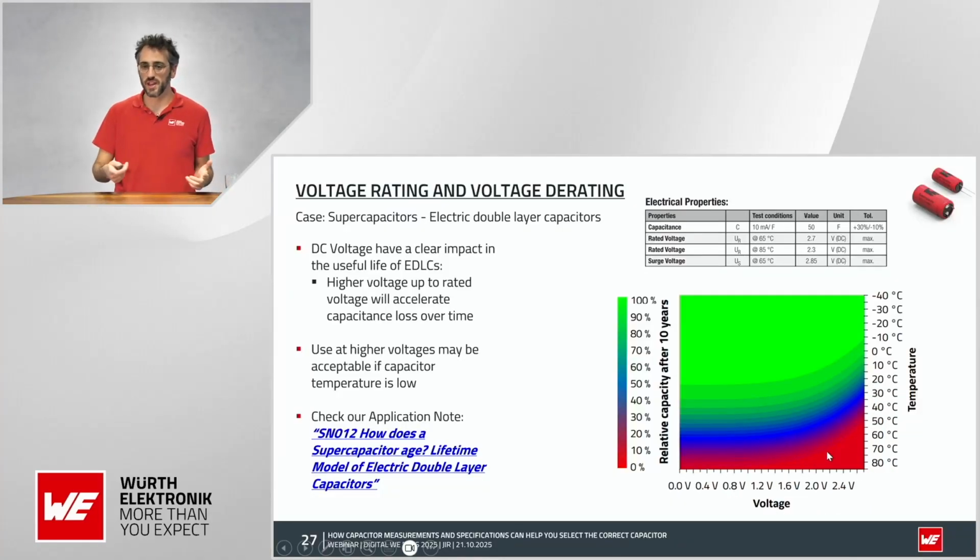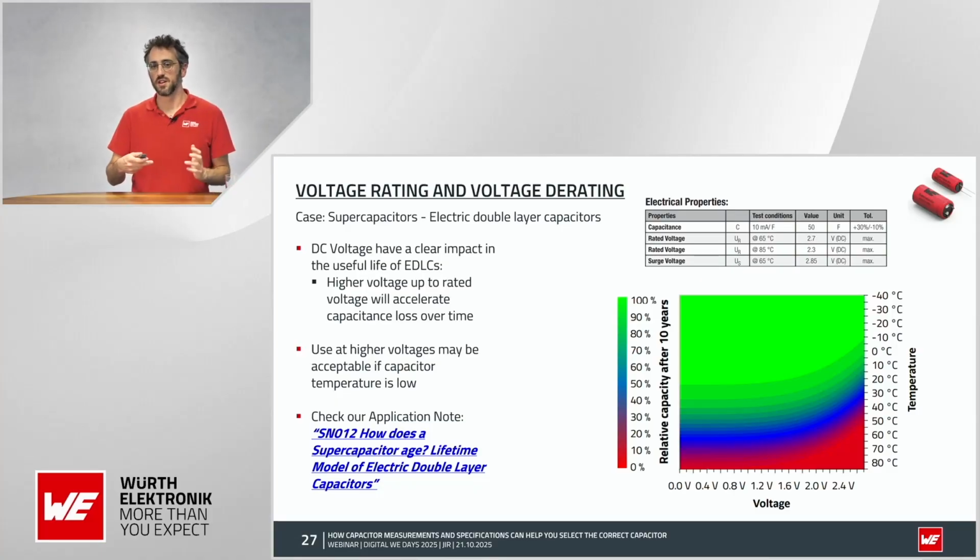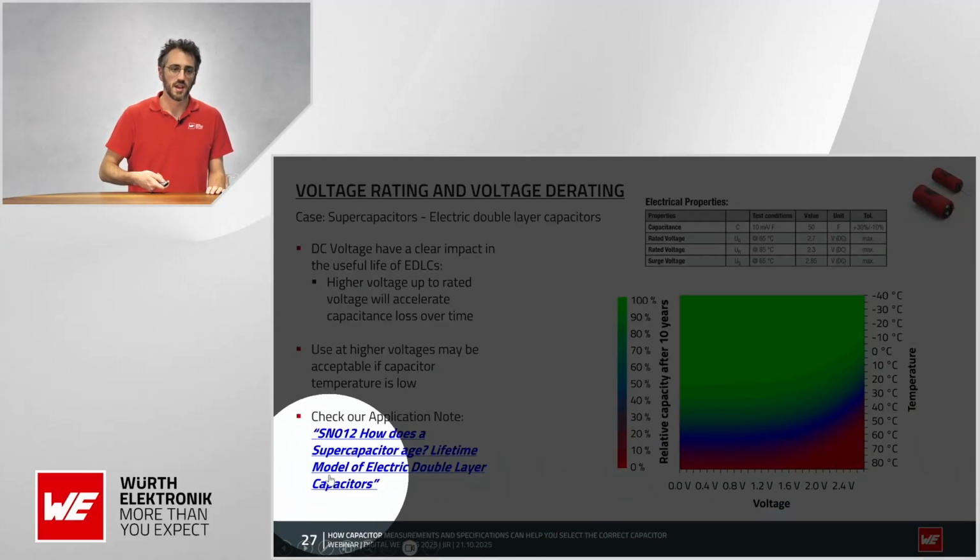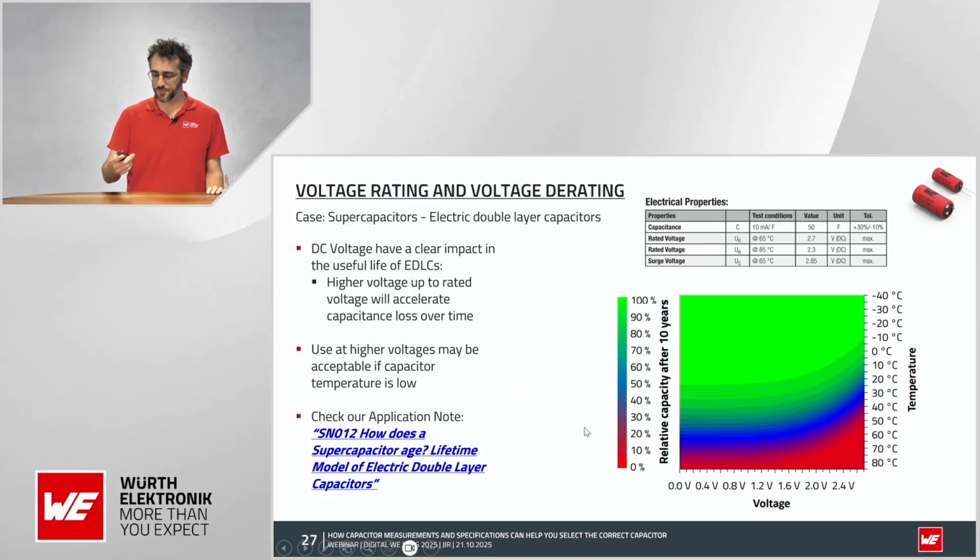So the interaction of temperature and voltage is what is affecting the lifetime of supercapacitors. So as I said, you can derate voltage at more temperature or less. And we also have an application note describing this process.